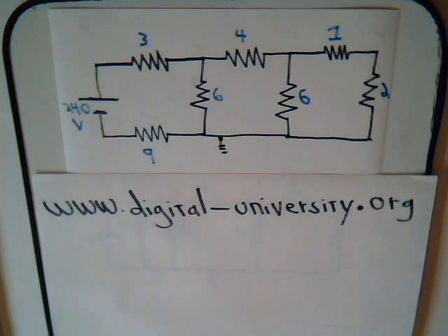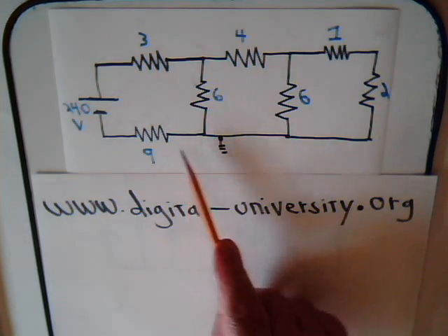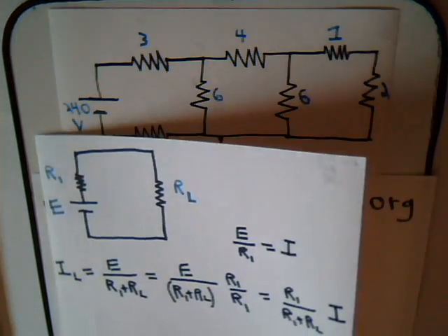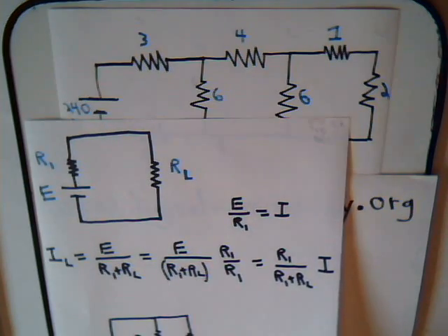Now for this problem, we can solve this quite readily. For this circuit here, we can determine the currents through all the resistors using the mesh current analysis technique, but we can also redraw the circuit and analyze it using the node analysis technique. And that's what we're going to do in this video, and compare and contrast once again the two techniques.